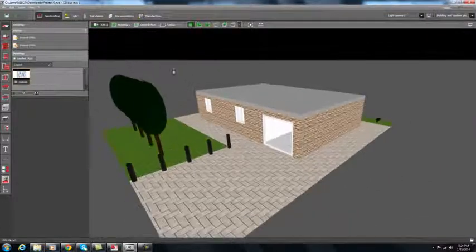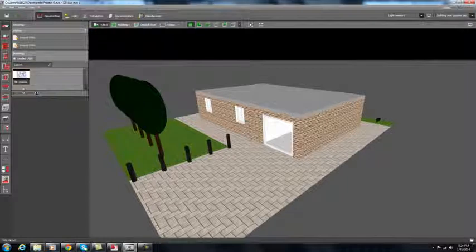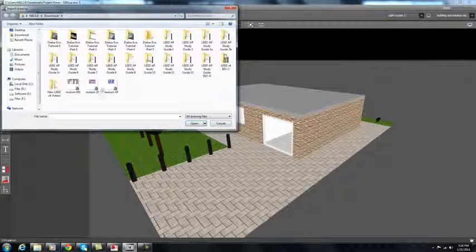The second floor. First, we need to import the second floor plan. So let's go back to this tab, import drawing, click the second floor, and then open. Before importing it, you have to make sure that you save your drawings into separate files like the ground floor and the second floor. So you will import it separately. And you have to make sure also that it has the same scale and it is located at the 0,0 axis. Okay, so let's select the second floor and say open.